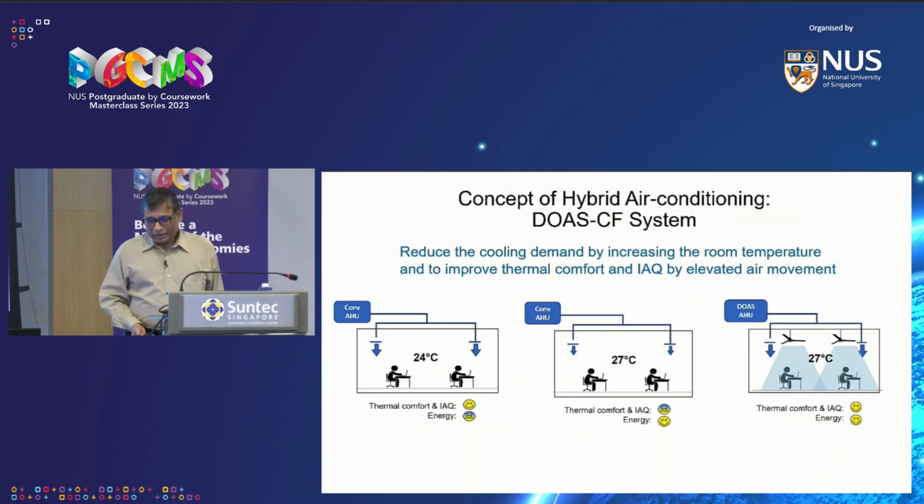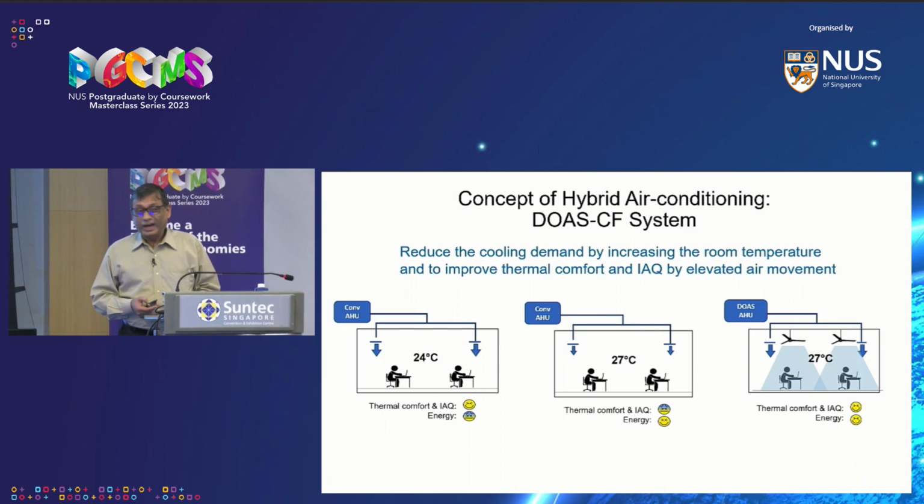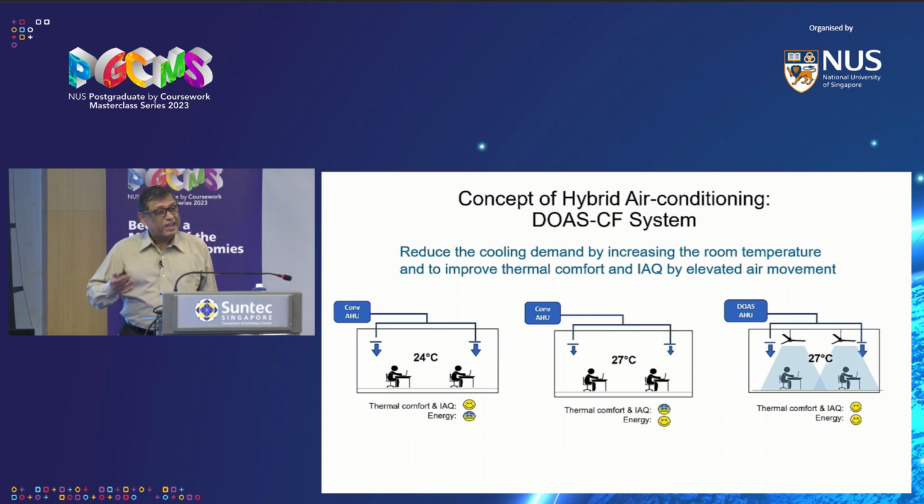There's some concept of how this building achieved that zero energy concept. We changed the notion of air conditioning. In this building, guess what temperature we maintain? 27 degrees inside the building. It's air conditioned, and we have fans. So 27 degrees with ceiling fans or pedestal fans. We have ceiling fans in the building, arranged, designed and installed as per the original plan. It creates nice, comfortable air movement that people are very comfortable with, and they like it. And no wonder, when we manage it the way it should be, we're also able to save all the energy that we produce and become energy positive.